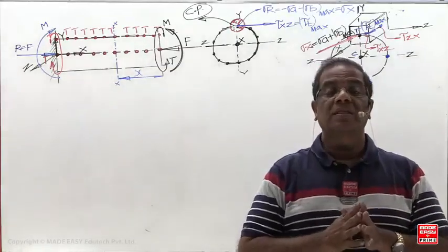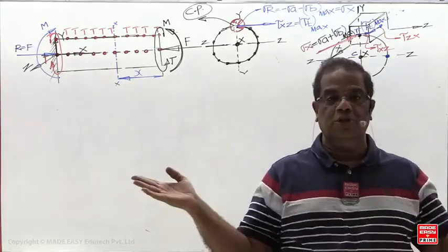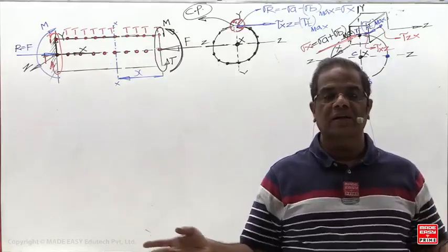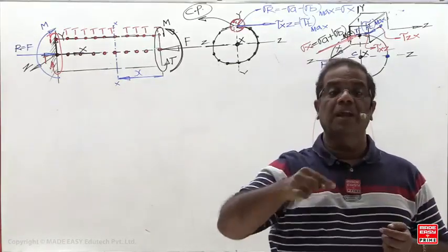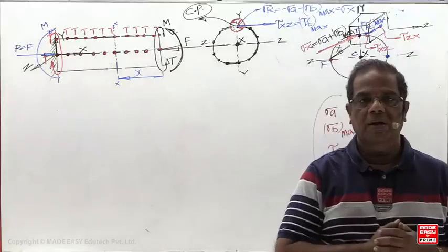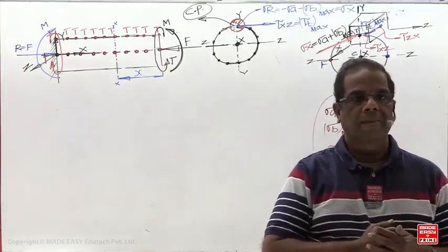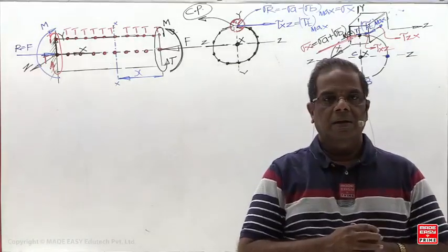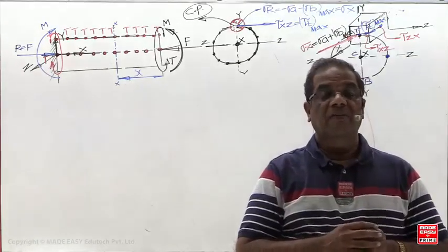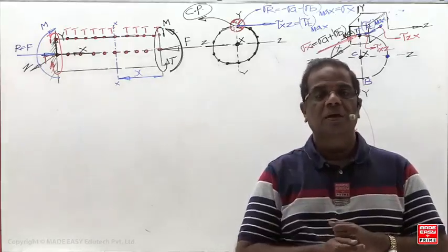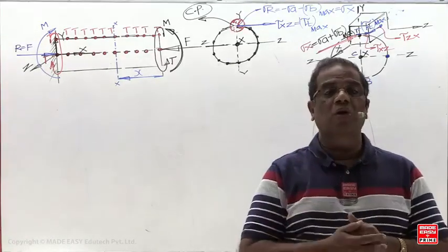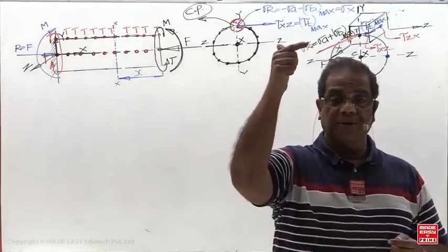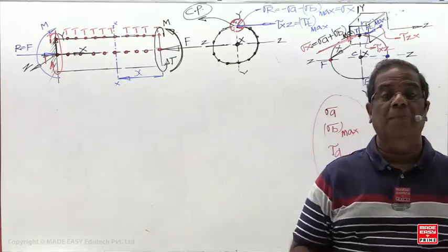And every point on the cross section is critical in pure torsion. This is incorrect. In pure torsion, any point on the periphery is a critical point. Next, the last one: when axial load, shear force, bending and twisting act simultaneously, either extreme top or extreme bottom is the critical point.